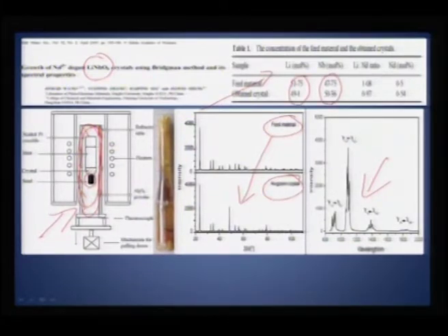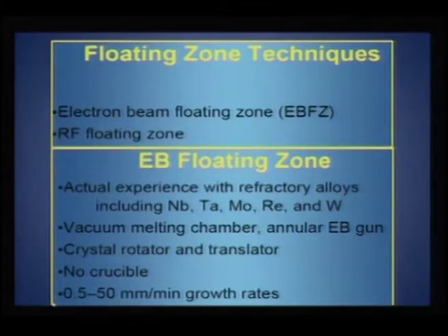Niobium content has a slightly larger mismatch, but the lithium to neodymium ratio is absolutely within an agreeable limit. So, this is a very important and the most preferred route for ferroelectric crystals. Therefore, the Bridgman technique is still being used for growing ferroelectrics.